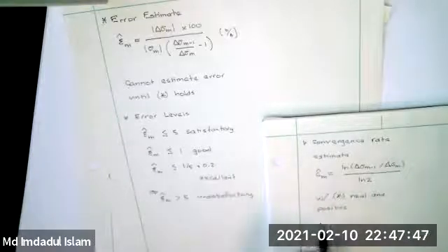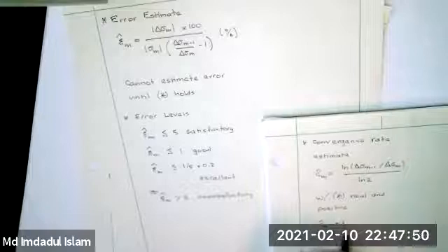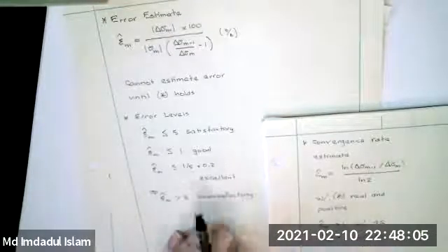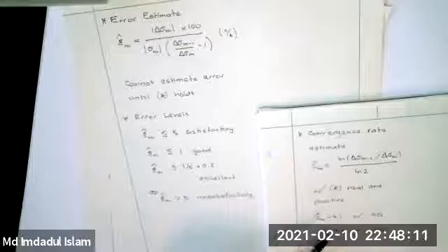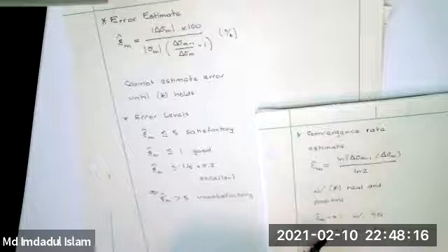Why this is of some interest: if you have 4-node quadrilaterals, which is what the 4Q stands for, then this convergence rate tends towards 1. That's because the missing thing in the elements is linear. The first polynomial missing from a power series expansion for the stresses is the linear term, and so that would tend to converge linearly as you refine the mesh with a mesh refinement factor of 2, which we've had at the beginning.